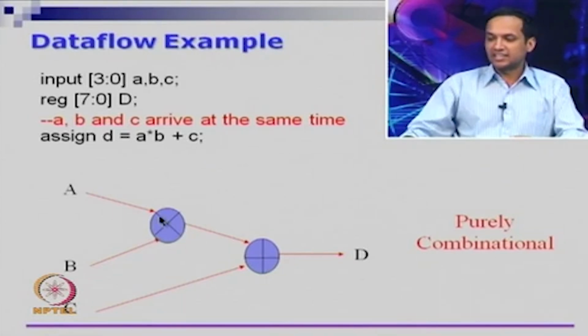So this plus is adder and this cross is multiplier. You could infer something like this by writing a line of code like this. You could also go and write this whole thing in a structural manner. By that, for the adder you may actually use a ripple carry adder, for a multiplier you may come up with your own way of doing multiplication of two numbers and so on. But if you do that, the programmer's intent is buried inside lots of lines of code, whereas this is very clean and many tools can immediately understand that you are looking for multiplication and addition.